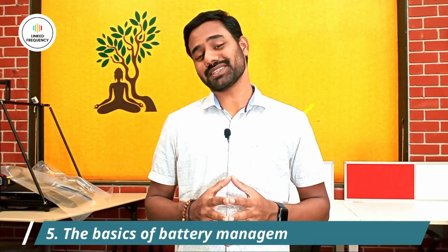Now it is a time to discuss the basics of BMS. BMS stands for Battery Management System. In industrial applications, it is not sufficient to control the charging and discharging cycle of a battery pack. Alongside, we also need a BMS circuit which controls various factors beyond the safety instructions. BMS basically provides the safety and security for the battery pack in every situation. For example, overcurrent discharge, over discharge of the battery, over thermal runaway or overcharging and over discharging. No matter what the case is, the BMS will take care of the battery pack.